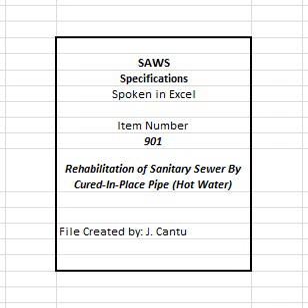3. Percentage ovality of original pipe, 2%. 4. Soil density, 120 pounds per cubic foot. 5. Traffic loads, HS 20-44 per AASHTO highway loading. 6. Soil modulus, 500 psi.